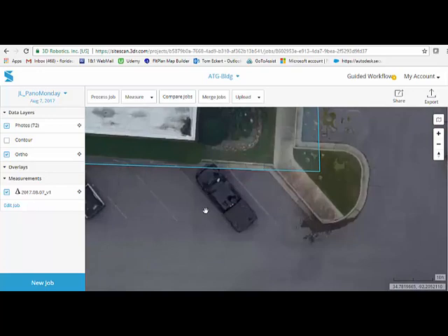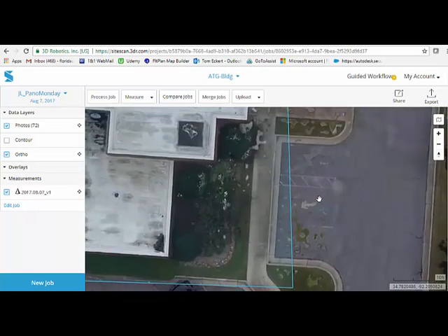So if we wanted to know the length of the handicap ramp itself, we can always go into measure, quick distance from the curb, double click on there, creates an object over here on the right hand side that tells you that it is a distance. When you click on it, it is 14.06 feet. Spec is 14 feet, so we meet or exceed the requirements for development. So we could do some parking stripe counting and different aspects.